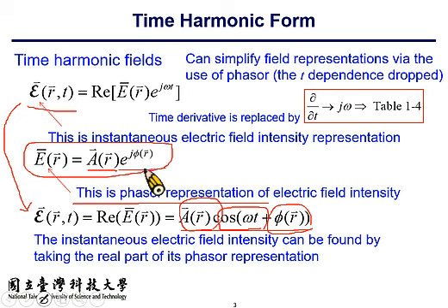Where is the time dependence? You don't see time dependence in the phasor representation, right? Well, that's the tricky part of the phasor representation. It assumes the signal is a narrowband continuous wave. So it does have time dependence. It's exponential j omega t.